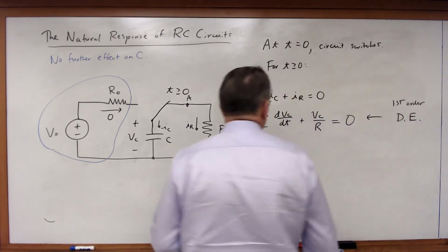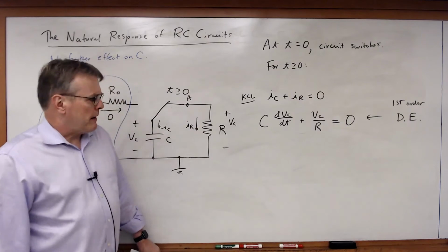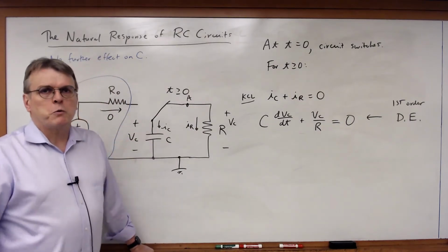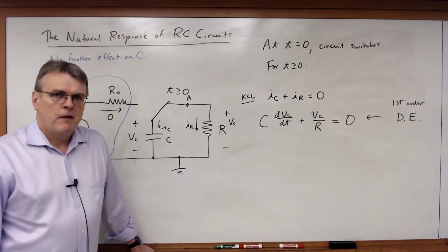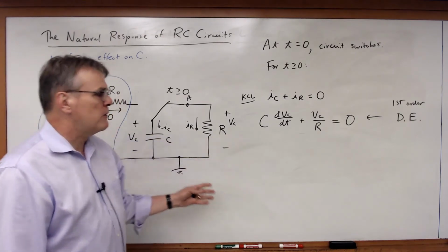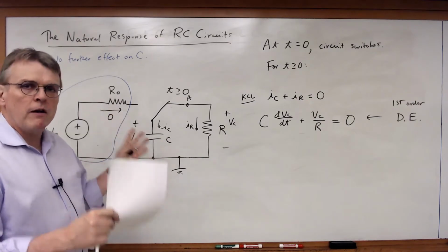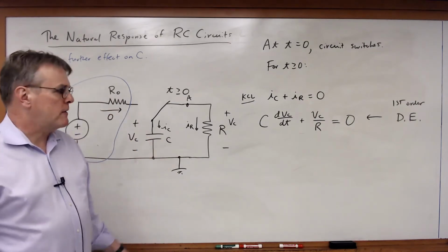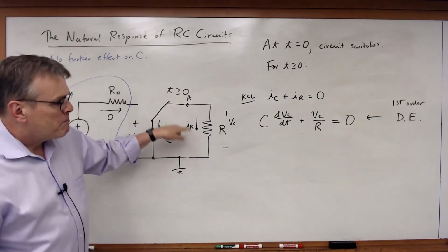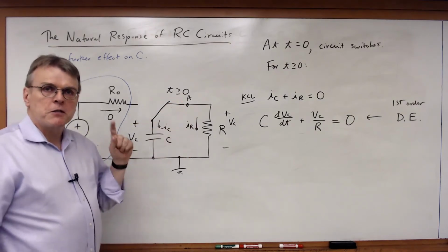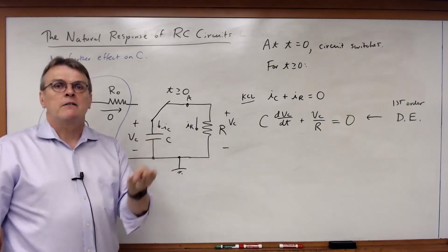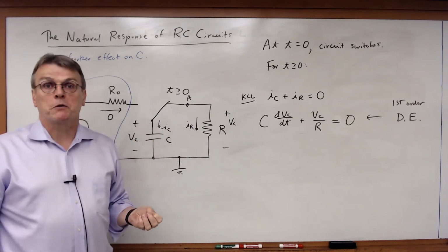Okay. Now here's the nice thing about this. I'm going to solve this first-order differential equation. But once we get the solution, that solution is going to apply to every other circuit we can come up with in which we can take the capacitor and basically reduce the rest of the circuit to a single resistor. So I only need to do this once. After that, the same solution works for every first-order circuit.